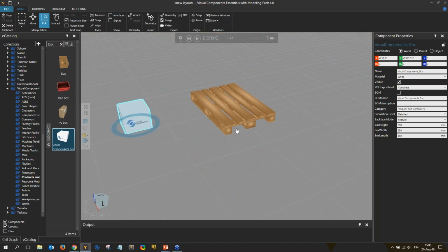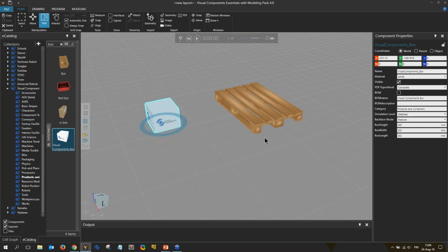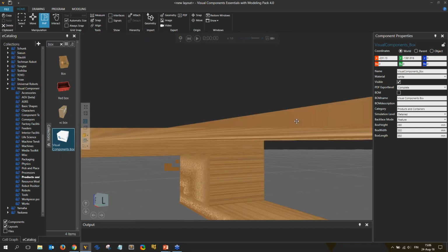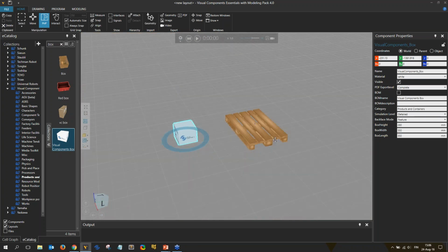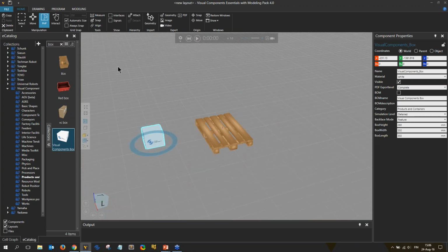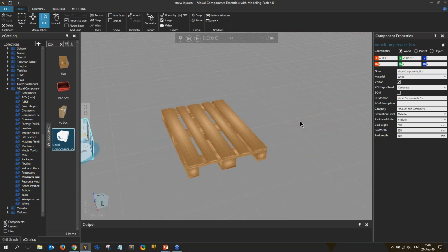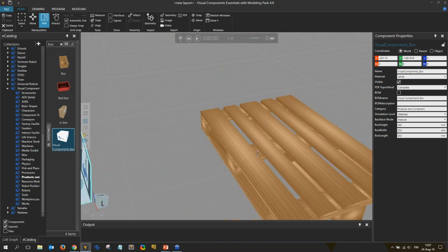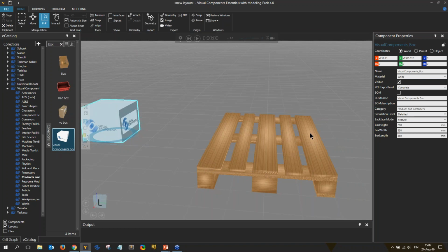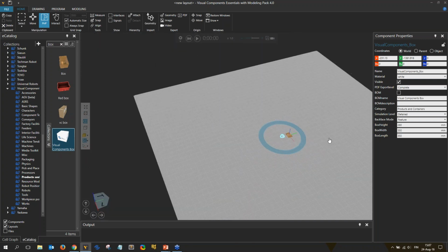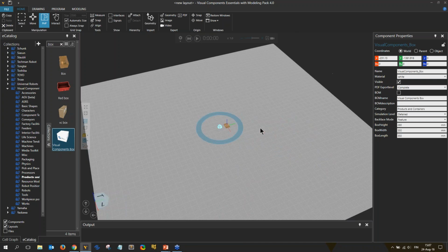Also it's nice to know how to center the world to some specific detail in your model. You can do that simply by right-clicking somewhere in the model and clicking Center in 3D View. Then it centers to that, and it zooms to that, and it orbits around that position. This won't work centering to the floor, so you need to be on top of the 3D model in order for this to work. And the shortcut for this is holding down your control key and right-clicking somewhere in the model. So you will probably quite quickly learn to just control right-click to go somewhere in the model. This gets more and more important as you're building bigger layouts, so that you can focus on a section where you're interested in.